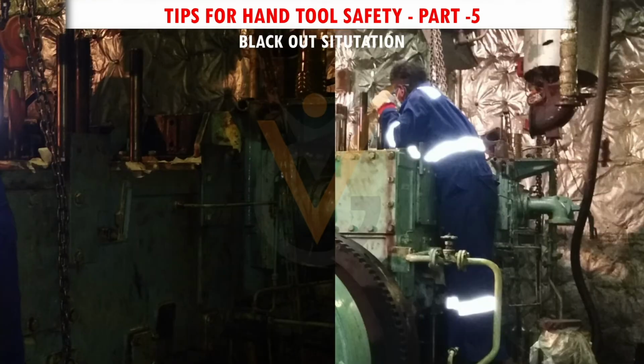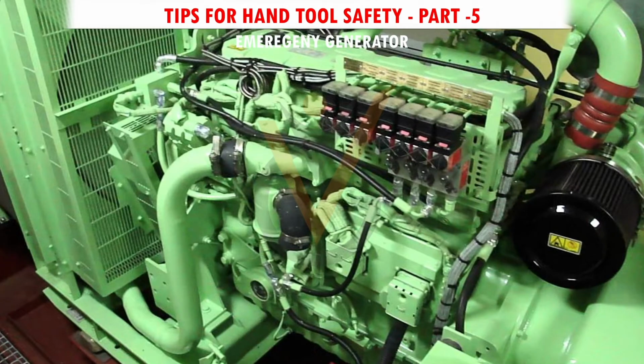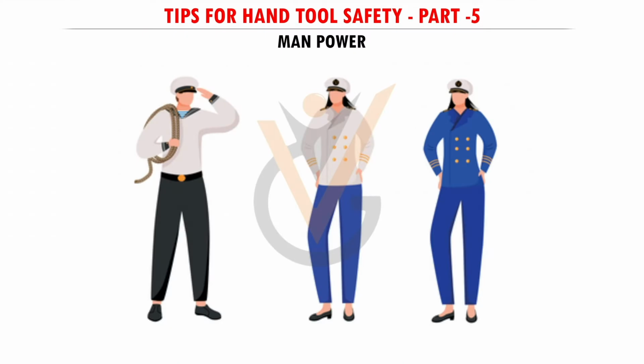In case of blackout, the following precautions and actions should be taken. Never panic in such a situation; be calm and composed. An emergency generator will restore the power in no time. Inform the officer on the bridge briefly about the condition. Call for manpower and inform the chief engineer.